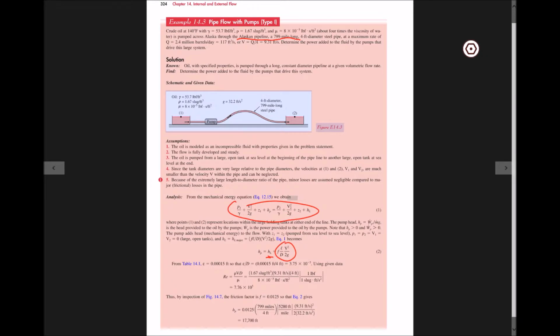We know that it is steel piping, so we know the Reynolds number, and we look again at the friction factor. The losses we calculate are actually pretty huge. In this case, we really don't need to calculate any minor losses, because this number is so huge with respect to the others that the geometrical shape of the pipeline won't really matter.